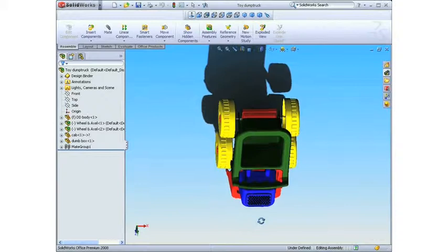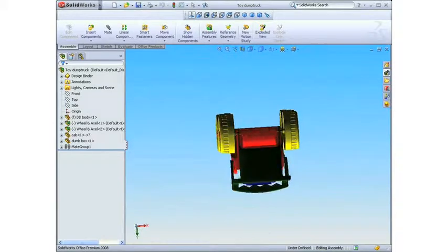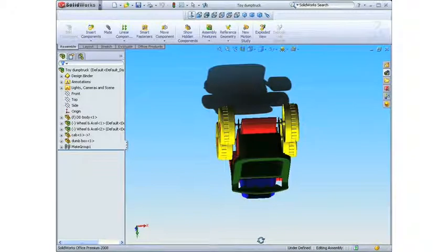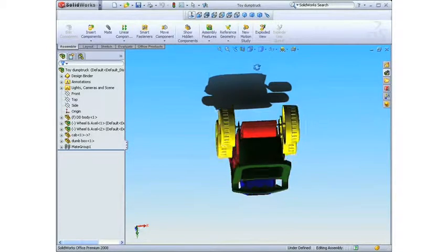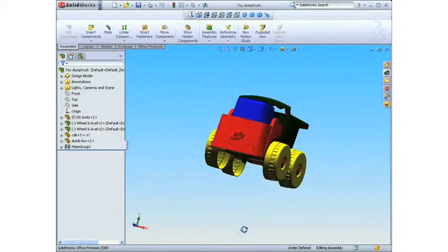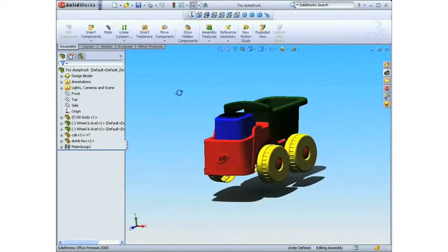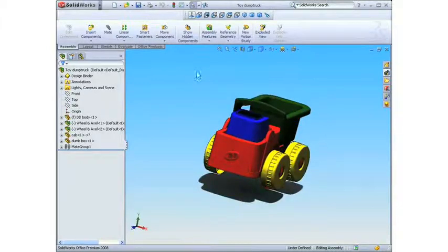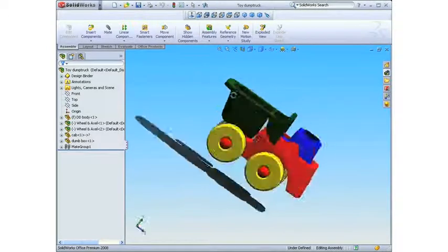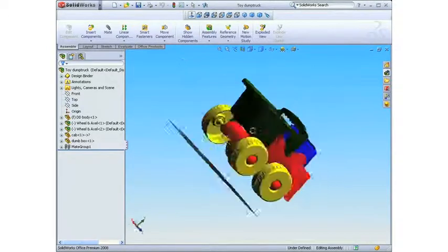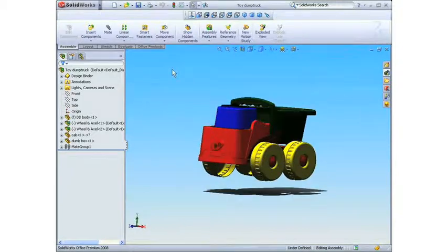Now at times you'll get all the way to the bottom of the screen and you can't rotate any farther. So you'll need to release, bring your mouse cursor back up to the top and continue rotating. At times, if you know where you want to rotate, with time you'll understand where to start your cursor movement so that you can get to the location you want to get to in one swoop.